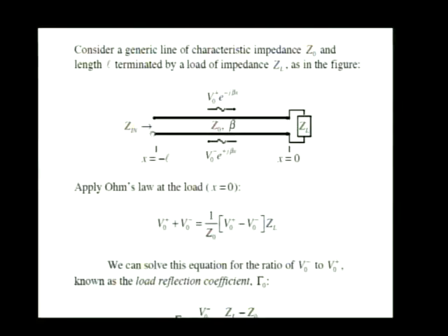section of transmission line. And of course, what the input impedance means for the circuit is that if this section of transmission line with this load impedance was connected up to another portion of circuit over here, I could replace the transmission line and the load by a single impedance, Zin, right there. And it would not change the operation of the rest of the circuit that's connected up to those terminals. So Zin is the impedance looking into those terminals.